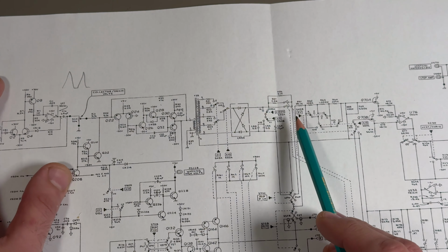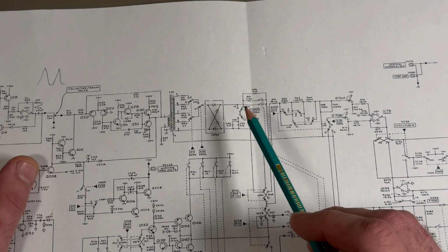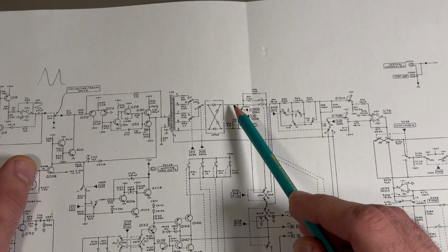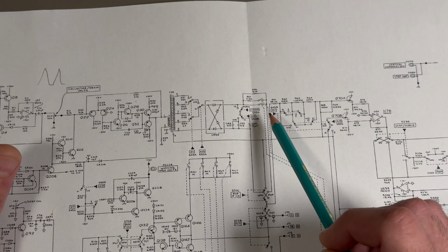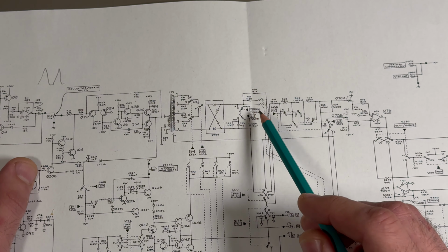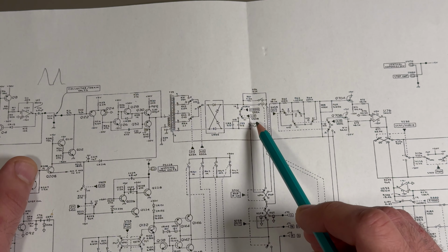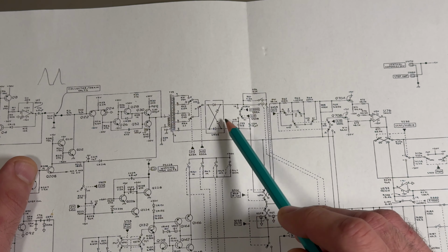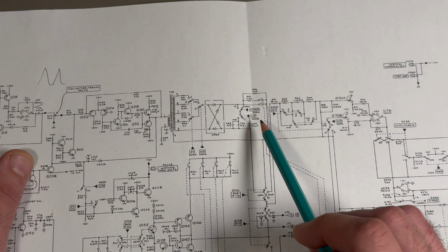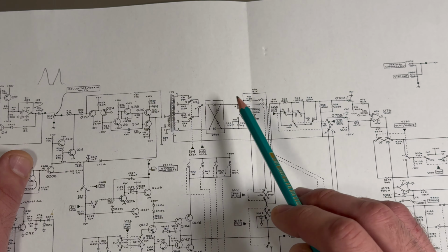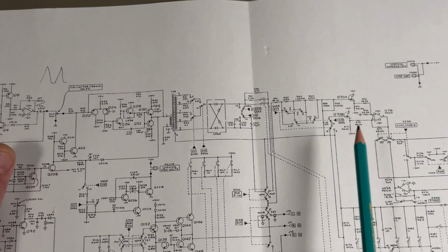And then yeah, you can see there's no filtering. That's because we want to have a sweep. So if you want a DC here, there is a mode that's used to test leakage currents of devices, and it actually filters the output so you don't get a sweeping characteristic curve of the semiconductor. You just get a bias point that you can move across.